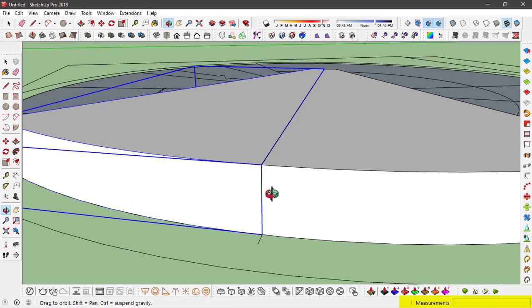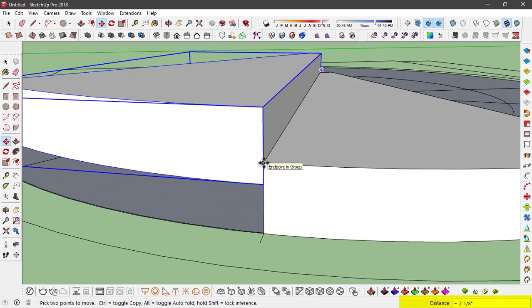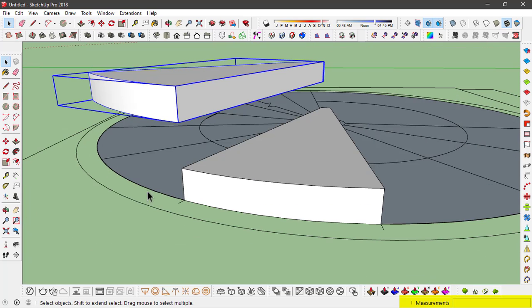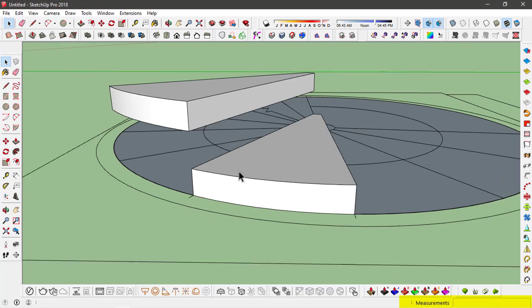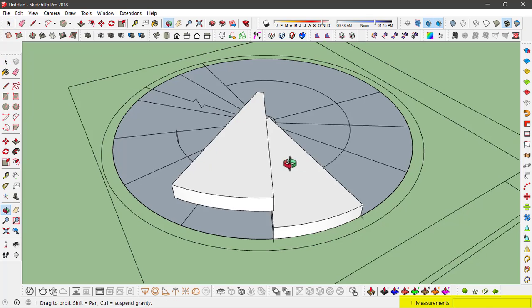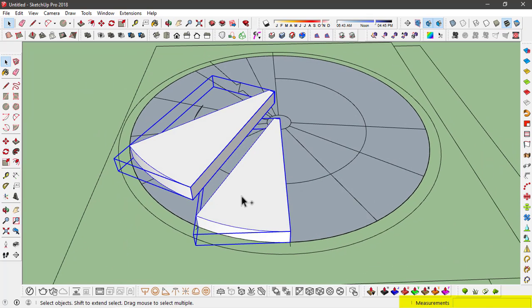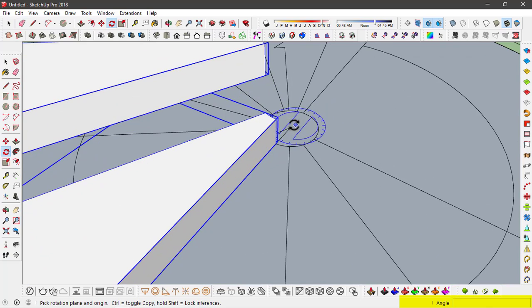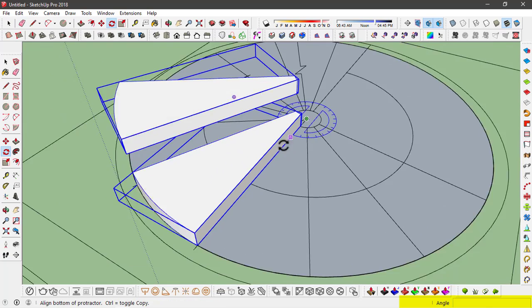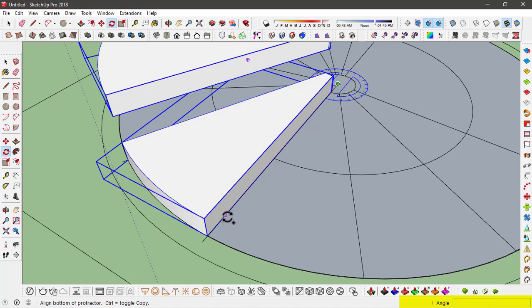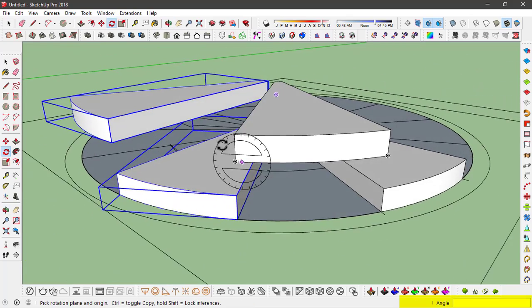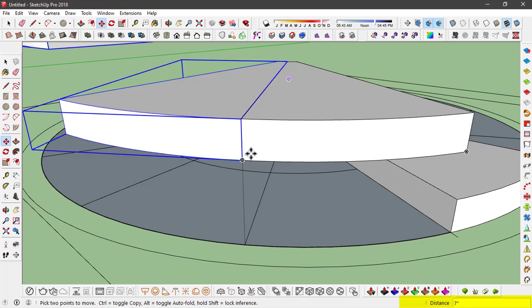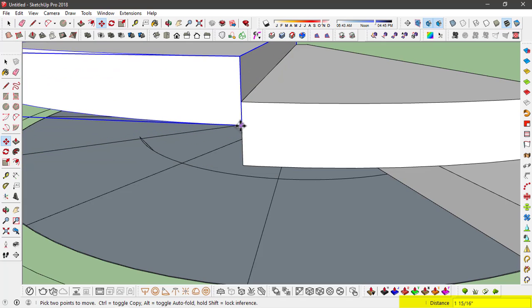And now I'm going to move this on the Z axis about 7 inches so that our riser comes out to be 7 inches in this staircase. And in a similar way we can make more copies of this. Just select all these steps and use the Rotate tool, snap it to the center point, hit the Control key, now to move this on the Z axis, use the Move tool, snap it to the other step, and from here move this further to 7 inches.